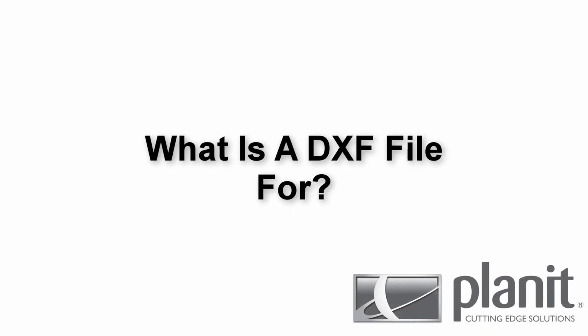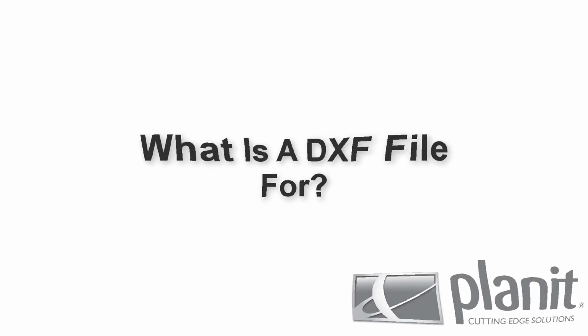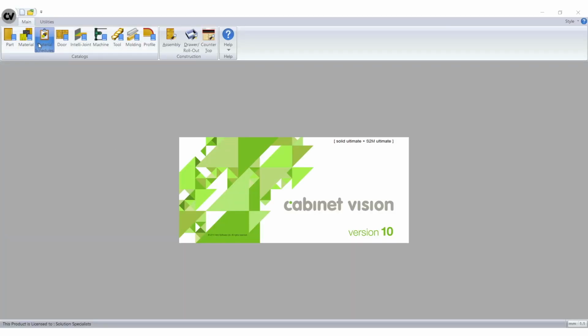A DXF file is used to transfer a file from a CAD-based program to the CNC. This will save you plenty of time when it comes to transferring the data from existing AutoCAD drawings. You may use it for such things as signage, a counter, or any uncommon shape you may need to construct. Right, let's get into it.